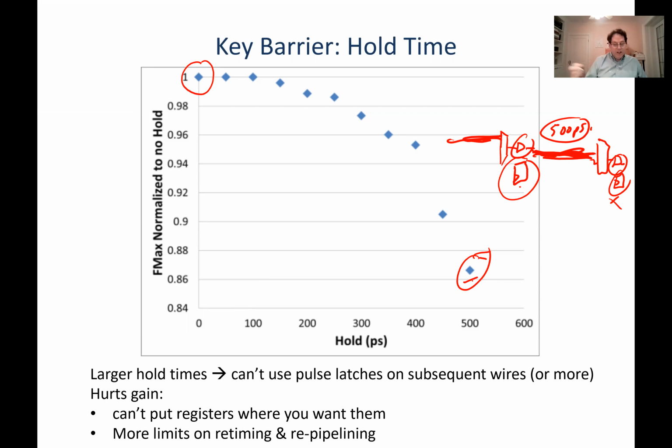So that's one of the key things, is that this technique is going to be impacted by exactly how good or how bad the hold time is on these pulse latches.